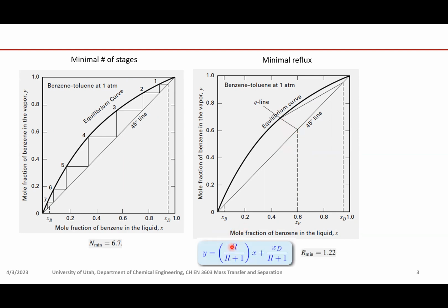for the Q line, we know the slope of the Q line is minus 0.637. So we can draw a straight line starting from that point with a slope of minus 0.637.